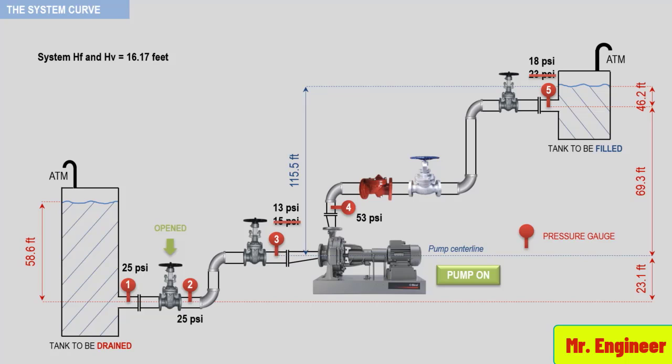It depends on the actual piping and all the system fittings, as they are now, and the next shift, and tomorrow, and next month. If a resistance load changes, it will be registered on the gauges. If the pipe diameter changes, it is recorded on the gauges. If new equipment is added, it is visible on the gauges. The pressure gauges and other instrumentation are the pump's control panel. You wouldn't drive your car without a dashboard.